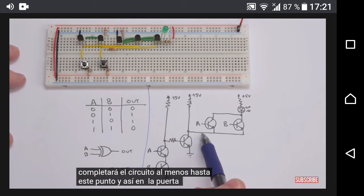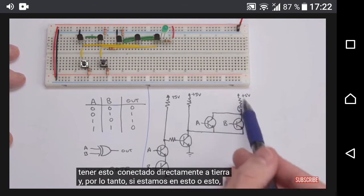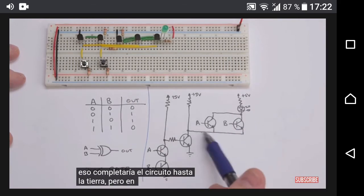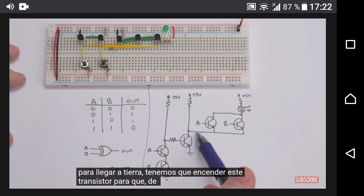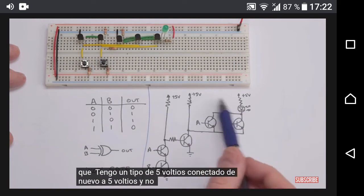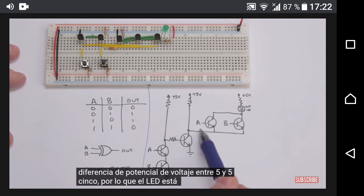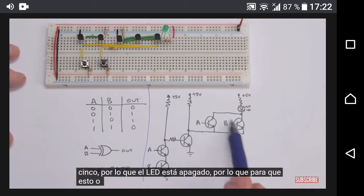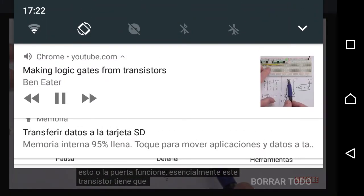And so in the OR gate, we just had this connected directly to ground. And so if this or this were on, then that would complete the circuit all the way to ground. But in this case, in order to get to ground, we've got to turn this transistor on too. Otherwise, we've got 5 volts connected back to 5 volts, and there's no voltage potential difference between 5 and 5, so the LED is off. So in order for this OR gate to work, essentially, this transistor has to be on.